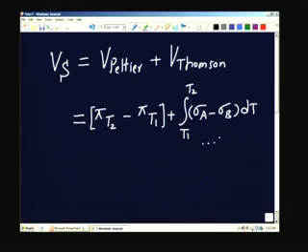We will call it equation 5. So, the Seebeck voltage is related to the Peltier EMF and the Thomson EMF, which would have occurred had we made the complete circuit and allowed a current to pass through it. So, this is an important relationship and it is a starting point for our discussion.